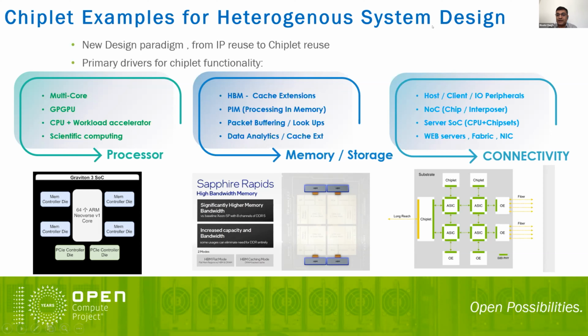Connectivity is more challenging as folks start discussing 25 terabits, 50 terabits of switch fabric. There, the reticle size of the die is a bottleneck, and people start distributing the features of the fabric by keeping the packet processing within the main core die and layer 1, layer 2 on the chiplet side.